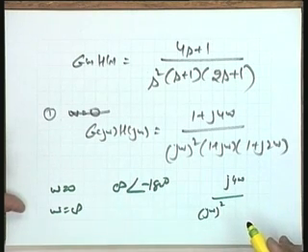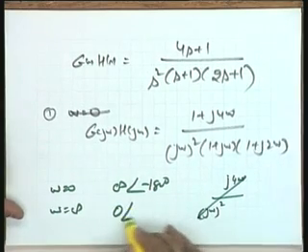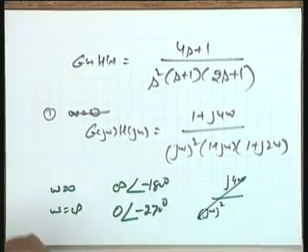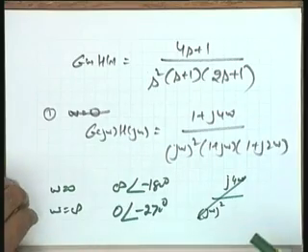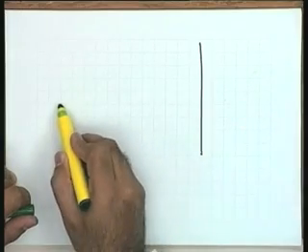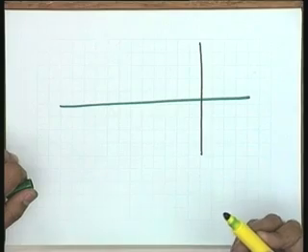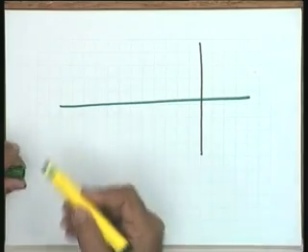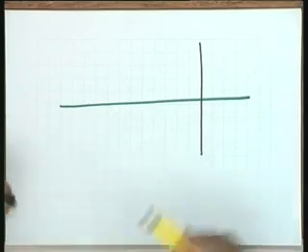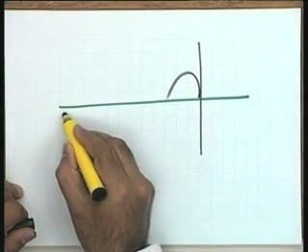Whether all of you got it, please? For omega is equal to infinity, the magnitude is 0 and the angle is minus 270 degrees, which is the same as plus 90. Is it okay, please? Of course, no doubt. Now, intersections with the imaginary axis. You will have to make it into a vector x plus jy, and from there you get the intersection. Since I know the result, I will give you the nature of the general plot. The nature of the general plot is like this.